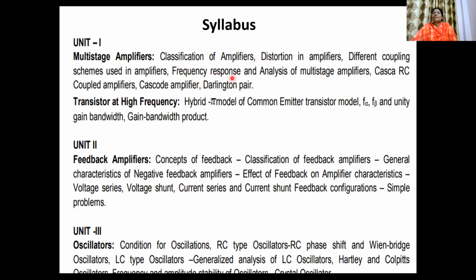What do we have to discuss here now? Here we have to find the lower cutoff frequency, upper cutoff frequency, and mid frequency region. For the lower cutoff frequency, we have to take the high pass output. For the higher cutoff frequency, we have to take the low pass filter. Anyway, the mid band frequency is almost constant.